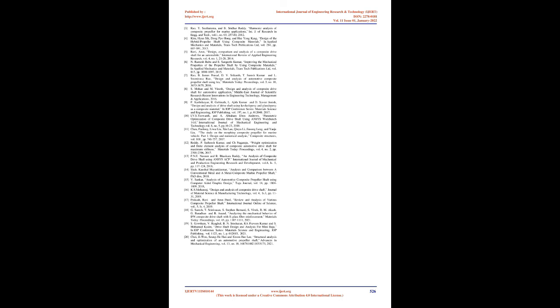This was accomplished by using composite materials to reduce the weight of the driving shaft. The mechanical behaviors and qualities of existing propeller shafts are investigated. Carbon/epoxy, boron/epoxy, and Kevlar/epoxy fiber matrix materials are chosen, and their characteristics are investigated. Ansys is used to evaluate mechanical behaviors such as torsion, buckling analysis, and natural bending analysis for existing propeller shafts, SM45C.